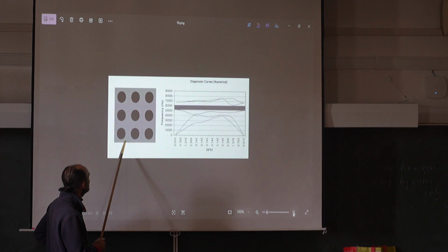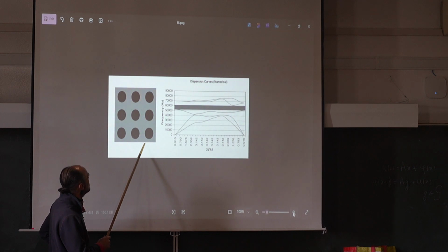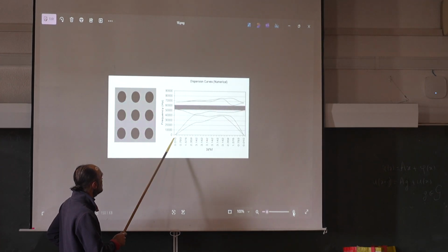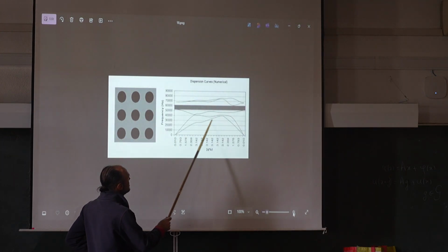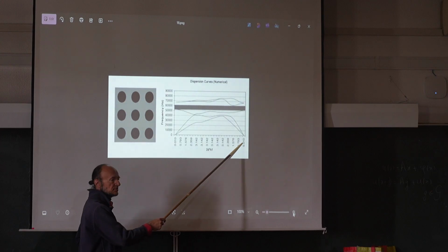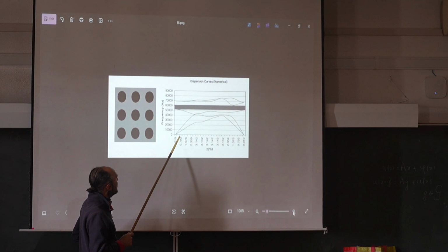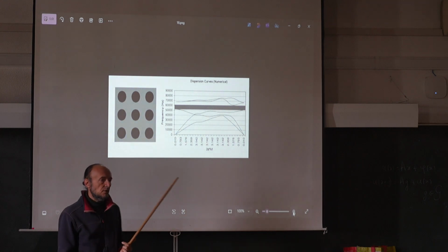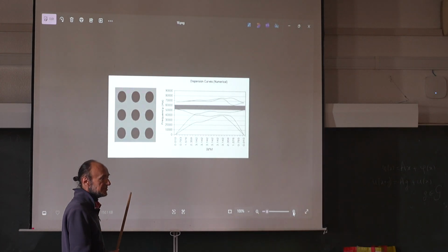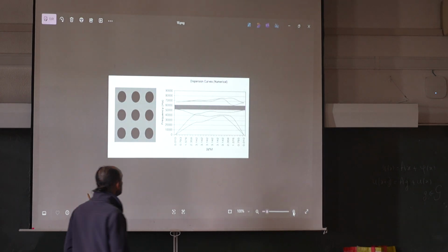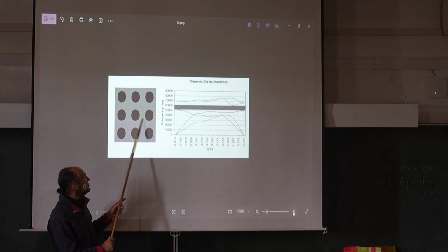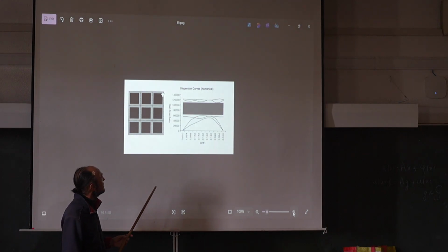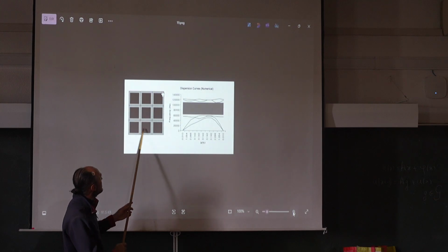So we made computations for an acoustic wave crossing through a matrix made of epoxy and with hard inclusions. And the main computation: this is the first eigenfrequency for different Ks. This axis describes the wave vector K. And this is the first eigenfrequency, this is the second eigenfrequency, this is the third one, and you have a gap here. So you have a region where the wave does not propagate, which is what we are interested in, right? And you can then manipulate the geometric characteristics of your periodic inclusions, and you can enlarge, or at least try to enlarge the gap. Here you see a much larger gap with larger inclusions.